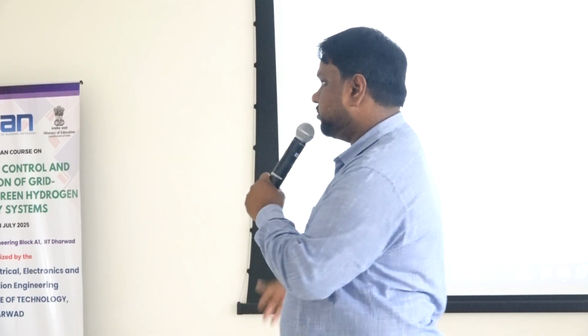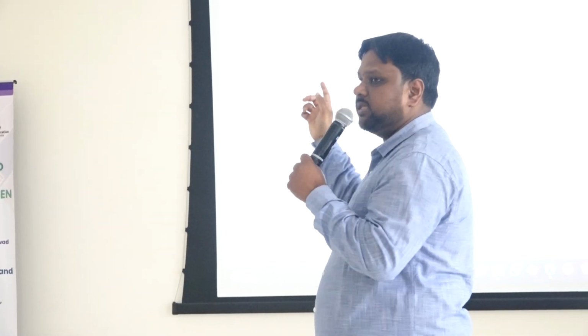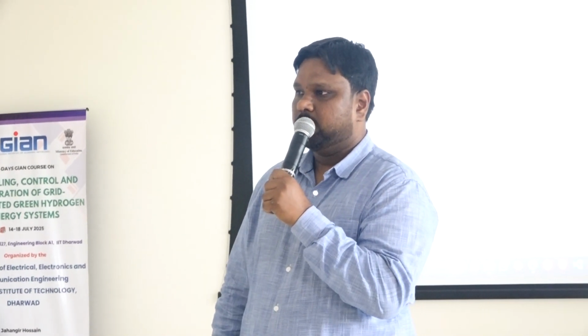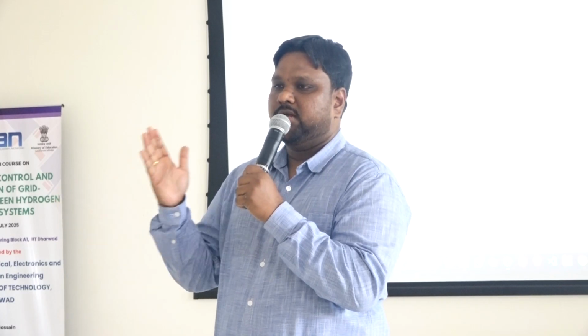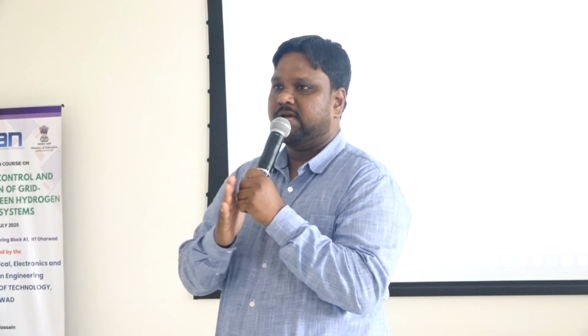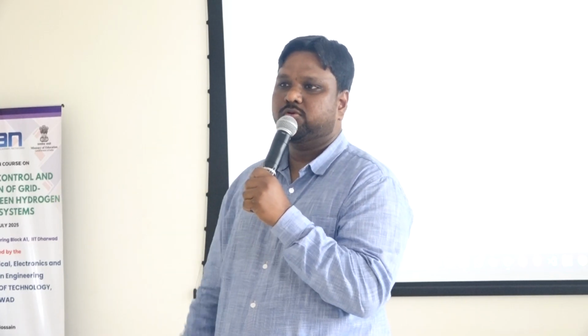Now the same pulse we are generating, but there is a way in which you give the pulse. In this case, if I generate a pulse, the same pulse I will give to my switch 1 and switch 4, because in the first time frame I want switch 1 and switch 4 to be active during the on period. If I consider the total cycle as T, during T on I want switch 1 and switch 4 to be on.